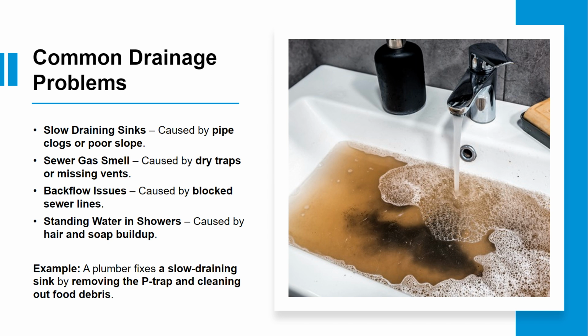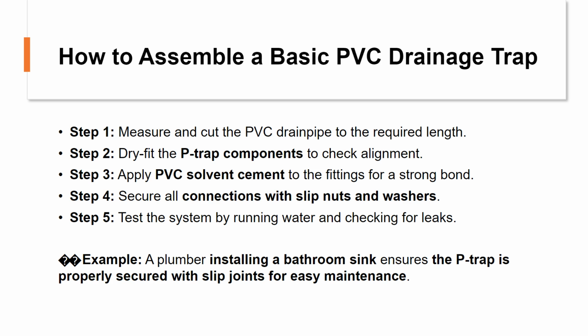Check your slope, seal your joints, vent your traps, and always leave the system better than you found it. Now let's get practical. I'm going to show you how to assemble a basic PVC drainage trap, just like the one you'll find under most kitchen or bathroom sinks.